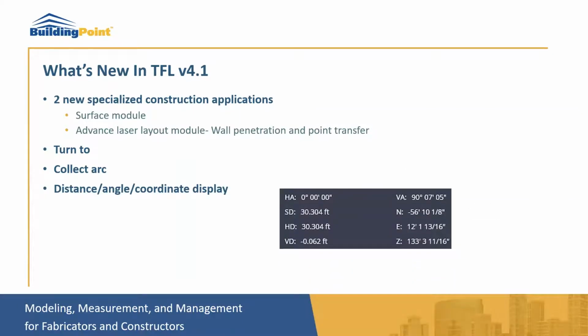And like I previously mentioned, they brought in the distance, angle, and coordinate display, available also in the device menu. So if you wish to know how far your rod is from the instrument, you can view it from the device menu.